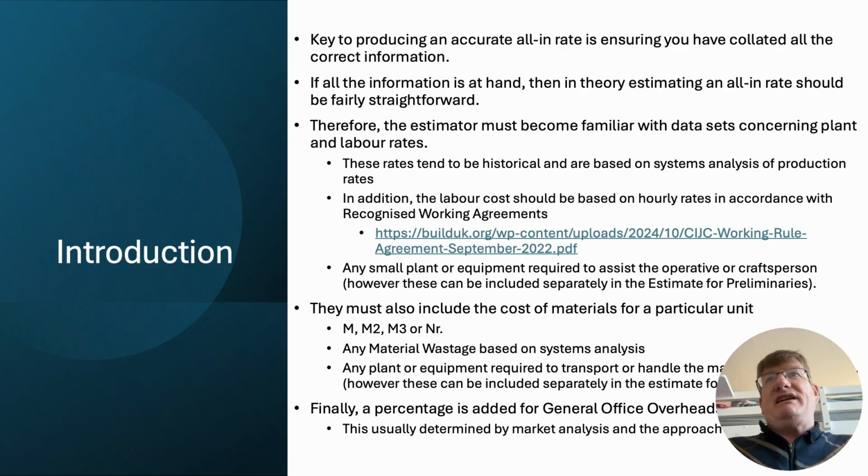A price for one brick is £1.50, and there are 59 bricks required in a metre squared. So you multiply it by 59, and then you add on a wastage figure, something like 5 to 10%. And then the same with blocks, where there are 9.8 blocks in a square metre. You could round it up to 10 blocks per metre squared.